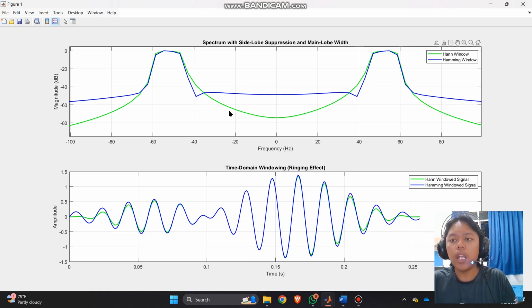Okay, for the amplitude at the edge, the Han window tapers mostly towards zero at the edge, providing better side lobe suppression and minimizing noise leakage. The trade-off between the two windows lies in their priorities. The Han window favors side lobe suppression over frequency resolution. Meanwhile, the Hamming window prioritizes better frequency resolution, but in exchange for increased side lobe level.